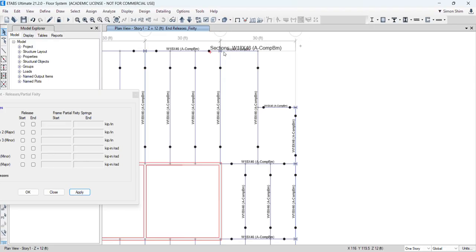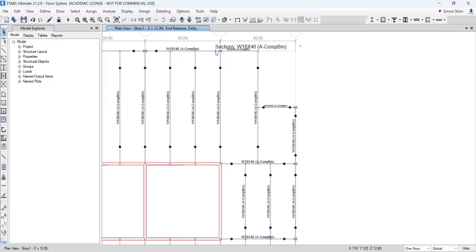So, moment release, moment connection. And typically when we have a moment beam, we need a backspan that also has a moment connection here on the right. So I'm going to select and, okay, remove the moment release here.